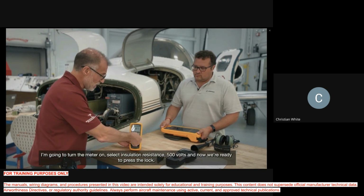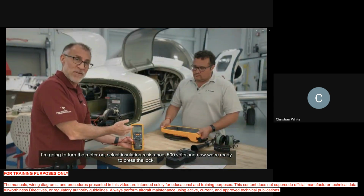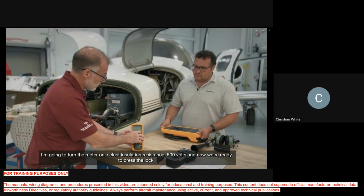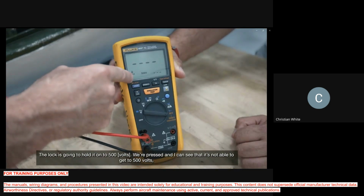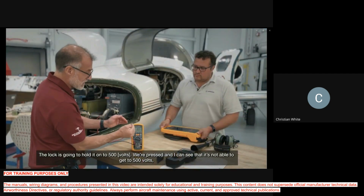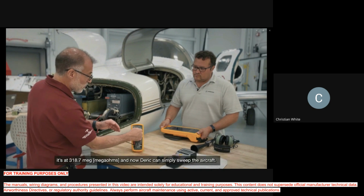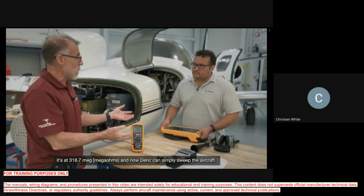I'm going to turn the meter on, select insulation resistance, 500 volts. And now we're ready to press the lock. The lock is going to hold it on to 500. We're pressed. I can see that it's not able to get to 500 volts. It's at 318.7 meg. Now Derek can simply sweep the aircraft.